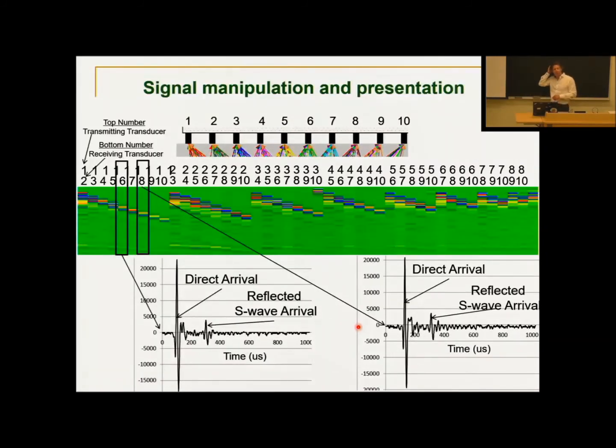But the idea with these is that we can have these sensors and we can fire them in a certain sequence. We can fire them all at once to get a big energy over a large footprint, thereby replicating a large aperture size and an improved lateral resolution, for example. Or we can phase them in sequence, that is, like firing at 1 and listening at 2 to 10, and then firing at 2 and listening at 3 to 10, and so on.